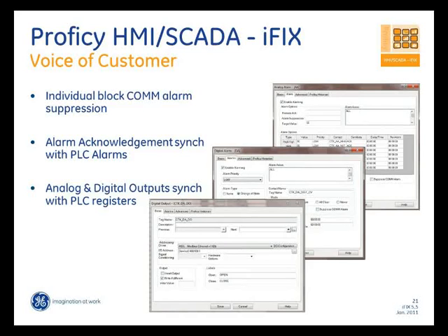So if you use analog alarms and digital alarms, and your contact tag name is actually a bit in the PLC where it also informs the PLC of alarm acknowledgements, then what we have done is that particular field, when an iFIX database starts up, is synced with the PLC register that you see. Or if there is a COM failure between iFIX and the PLC and it comes back up, before anything being written out, it is first synced.